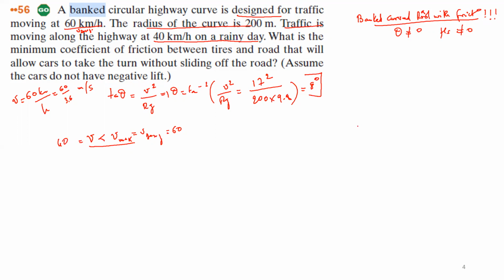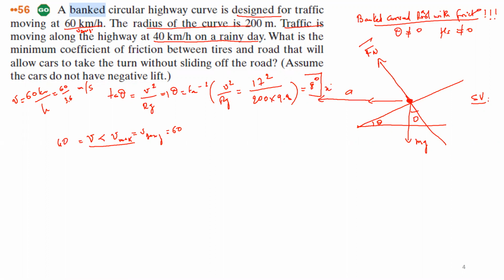Let me show you that. So this is my side view. Okay, this is my car. The weight is downward. The normal force is normal here. Okay, the acceleration is centripetal, horizontal here. And of course, this is my angle theta. Of course, the same angle theta is coming back here. I will choose this as my x-axis because I want the acceleration to be purely along x. Now, this is my y-axis here. So of course, this same angle theta is coming here.